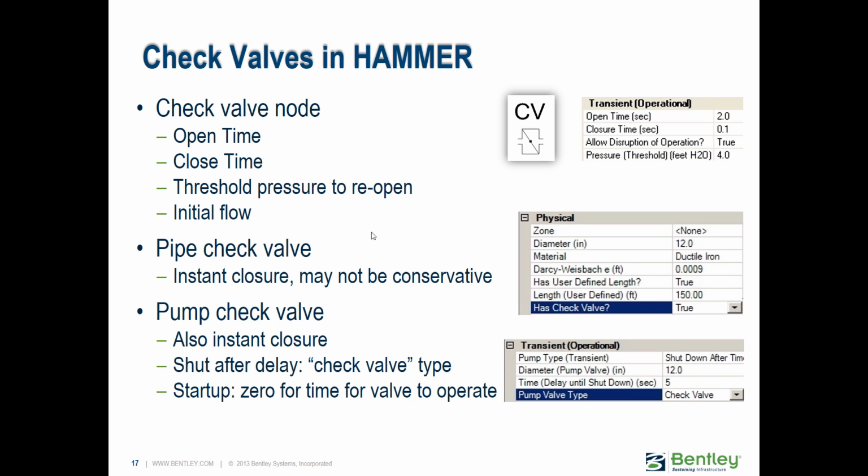In this slide, we're showing you the different ways. The first one is to explicitly model it as the check valve node element, and that's the most complex way to do that, because you're able to enter an open time and a close time, the time it actually takes between when it senses reverse flow and when it actually closes, and vice versa, and also a threshold pressure to reopen. Sometimes you need some amount of pressure to actually reopen a closed check valve.